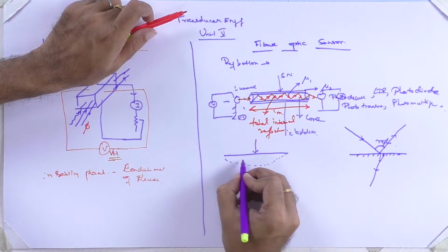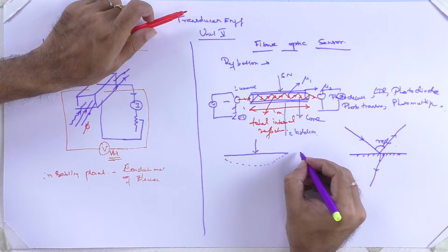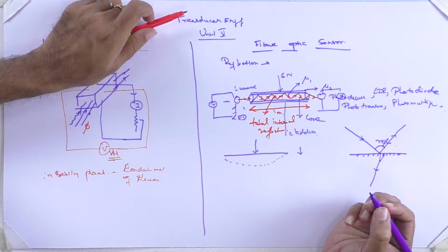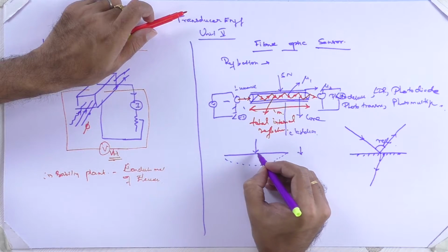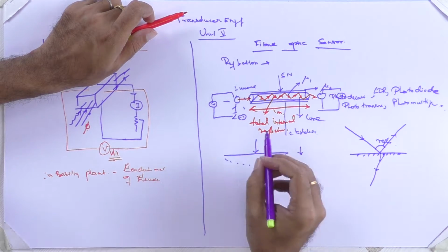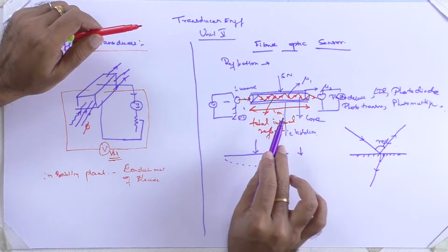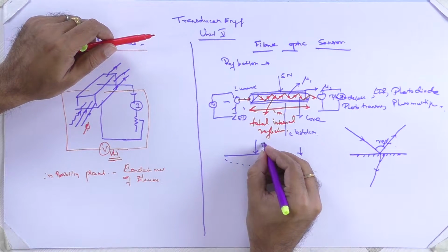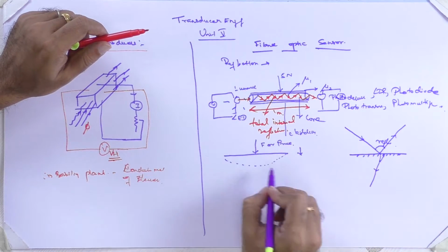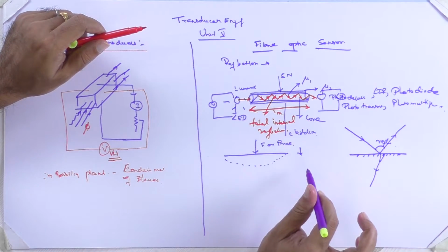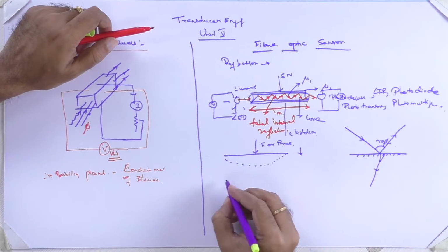Okay, then this reflection, the intensity on the received side will be low. It will be different or it will decrease. This decrement in the voltage is proportional to the amount of force that is applied to the fiber optic cable. Okay, this is the main property of the fiber optic sensor, where we are going to measure the force or pressure. This difference in the voltage or the reduction in the voltage is proportional to the force or pressure. The next construction is for temperature.